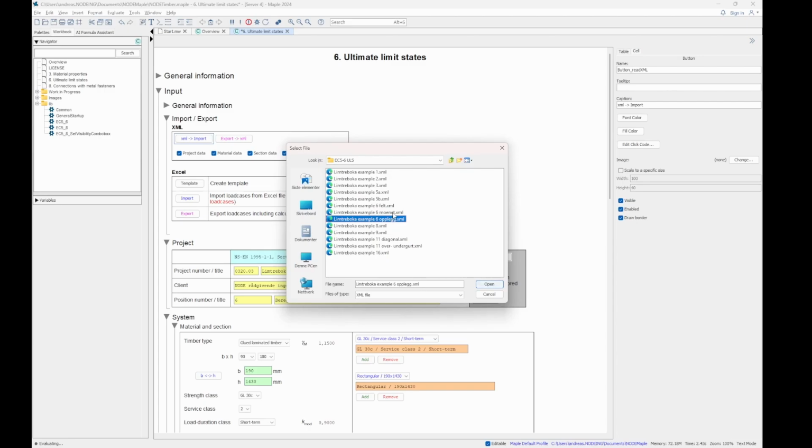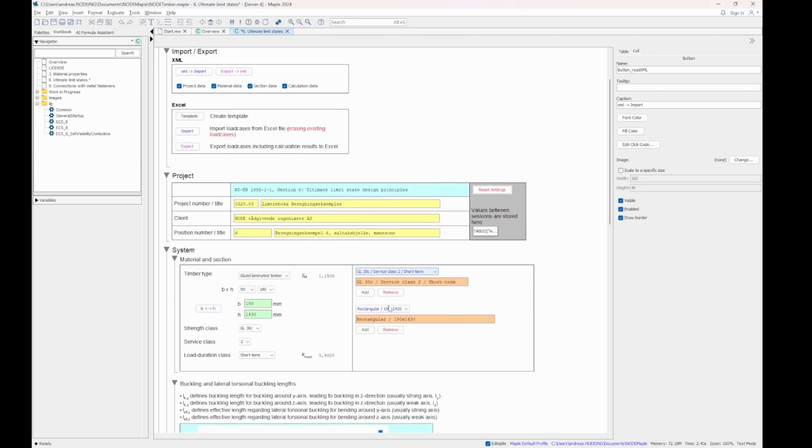We need to check the section in the middle of the beam with its specific checks according to the Eurocode. We do have the section, of course, at the supports, where we probably might have a shear problem. And we need also to check the maximum tension or compression of the outer layers of the glulam beam, as I've shown you previously, with the calculations for a single tapered beam. So let's just start in the middle of the beam, the biggest section with